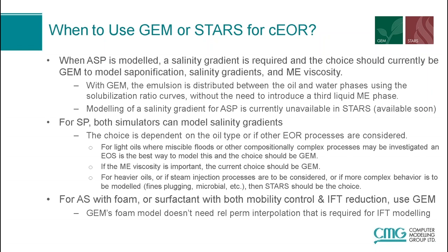Now for alkaline surfactant with foam or surfactant with foam with mobility control and IFT reduction, the choice should be GEM. And that's because GEM's foam model doesn't need rel perm interpolation, and therefore the rel perm interpolation can be used for IFT modeling.